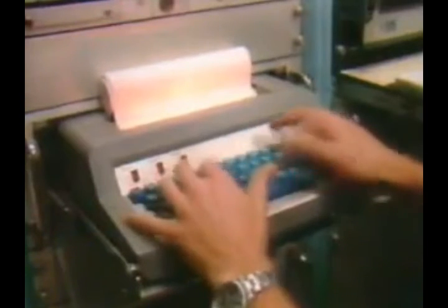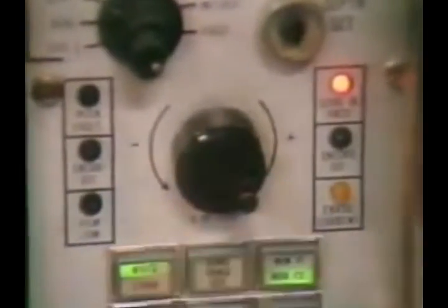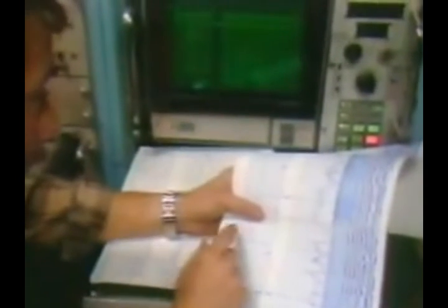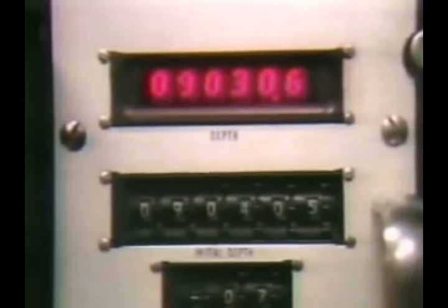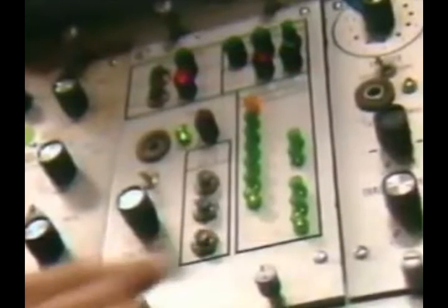Here is where a few odd-sized casing joints run in the vicinity of the productive zone will be helpful in distinguishing one collar from another. Starting below the perforating depth, the collars are logged up the hole and the log is correlated with the PDC log. Any necessary depth correction is made to the odometer. The collars are logged again, and the match checked by shifting the log one collar length in either direction. With a gun assembly on depth, the collar locator is positioned at the designated depth and the gun is fired.